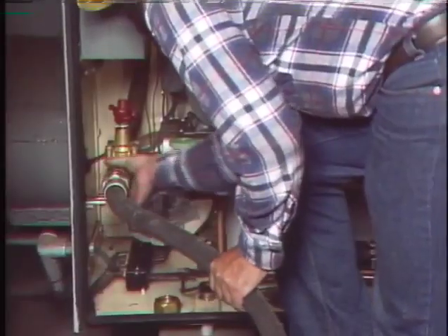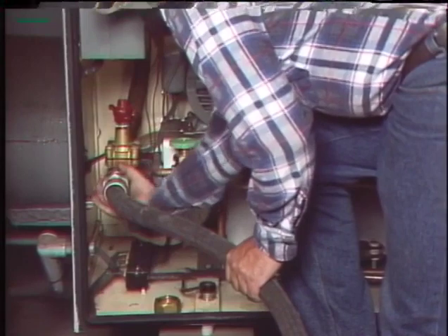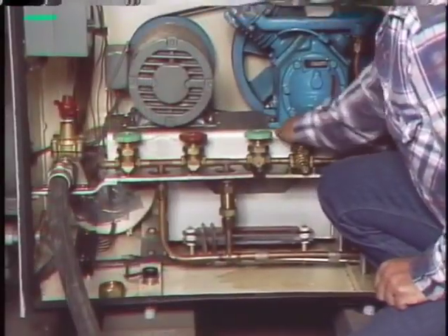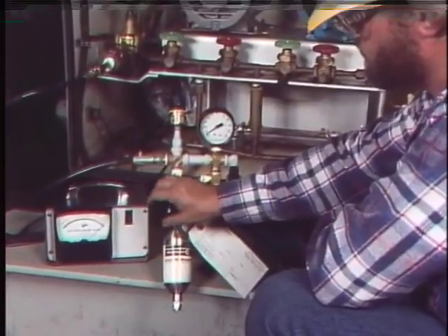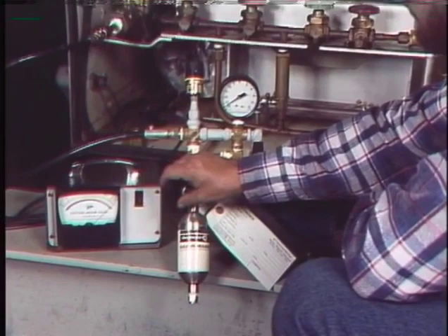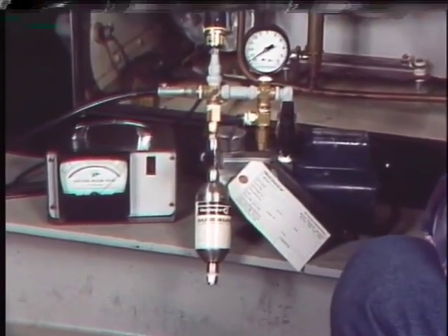To refill the breaker with gas, pump the air out of the breaker, drawing a vacuum. Then the appropriate valves are opened and the breaker is filled with gas. In most cases, after the breaker is refilled with gas, a gas sample is taken to be tested later for moisture content. So some of the maintenance tasks that are unique to gas blast breakers include evacuating the gas, checking the high pressure system for leaks, servicing the filter, and taking a gas sample.